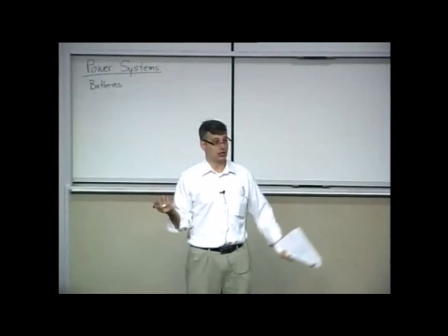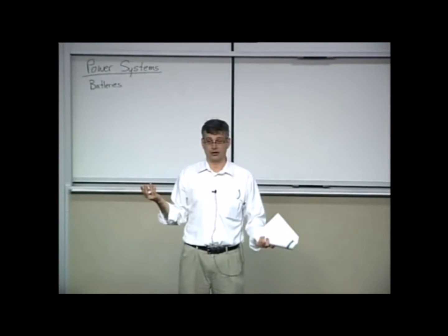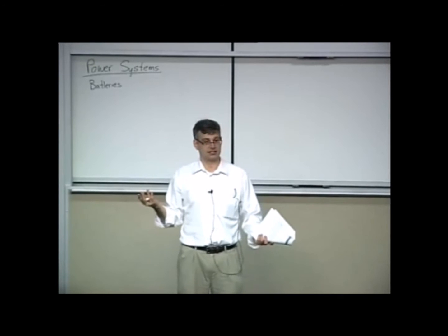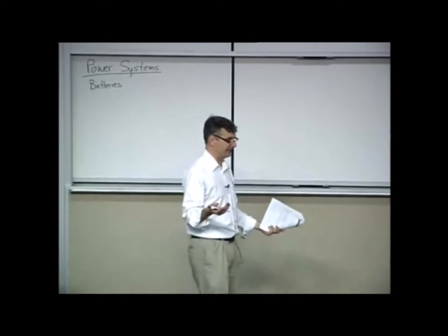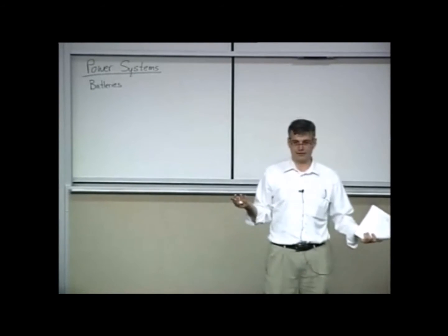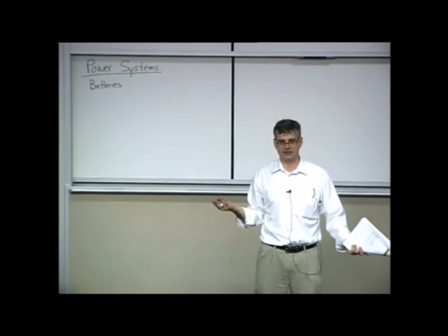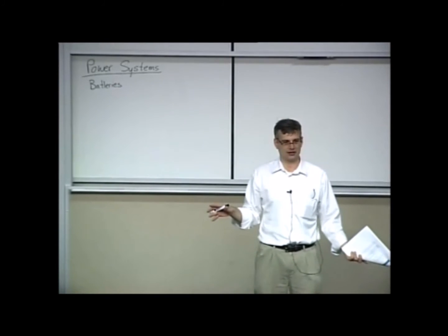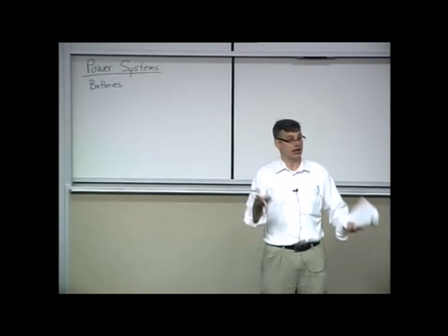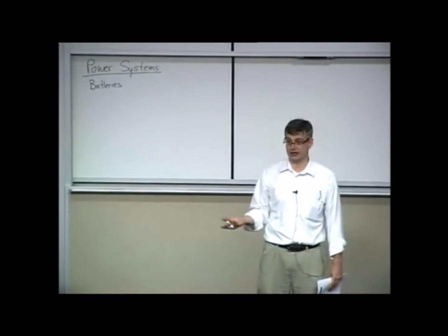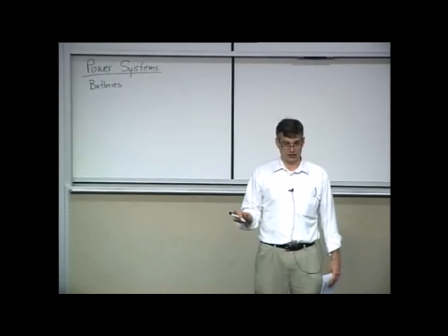For example, let's say you've got your 3-axis stabilized satellite, and for one reason or another, it gets misaligned and the solar cells no longer point towards the sun. Well, now you've just lost power. Or if it passes by the shadow of the Earth. Maybe it's in geostationary Earth orbit. You think, well, that's far enough away.